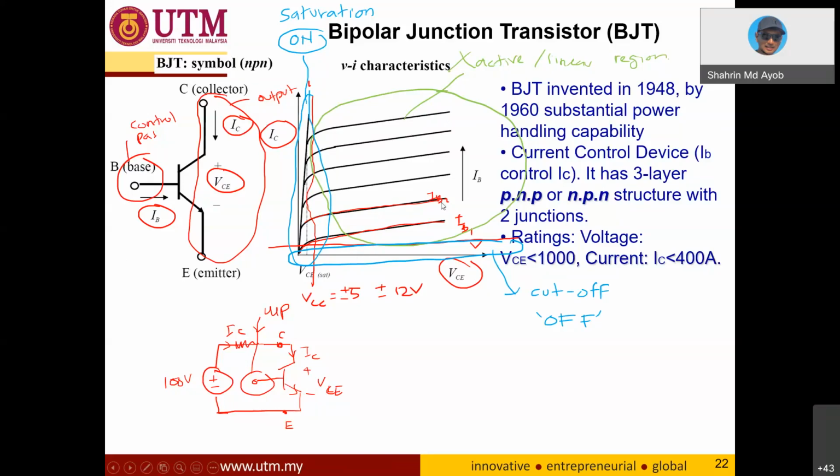The transistor can be either PNP or NPN. And on the rating, the voltage rating, just to highlight, this VCE of 1000 volt is not the forward voltage. It's not the voltage drop across the VCE during on. This is the rating during blocking, or during V off. When it is off, it is the highest voltage that it can block.